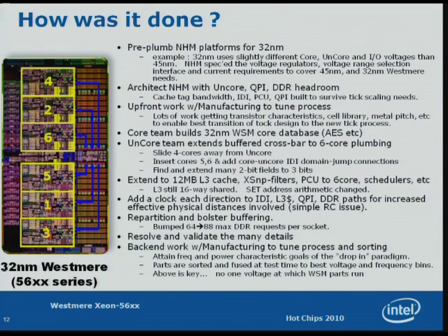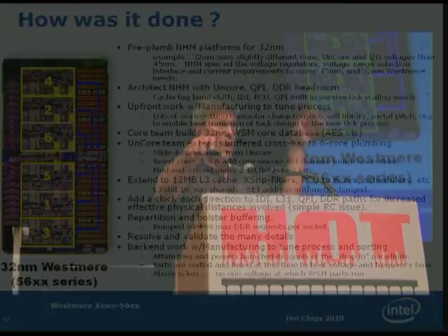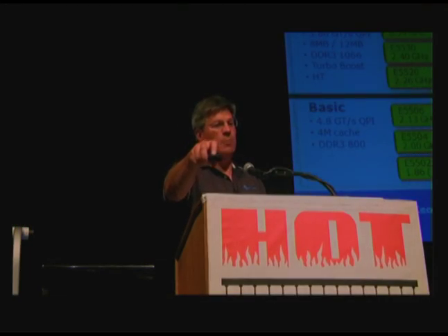And then the last part I hit here is there's a great deal of effort that goes on with the manufacturing team. After all of the design is done and we've got this part, the manufacturing team just does a phenomenal job at Intel figuring out how to bin and tune up these parts. And as I mentioned, they don't actually even run at the same voltage. They're tuning the voltage for the leakage and the characteristics of each of the die as they come flying through the fab there in order to make these parts fit into the drop-in philosophy we were trying to accomplish.